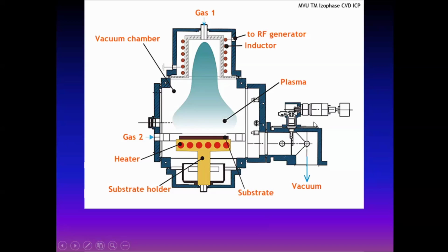So a few of the advantages of CVD: we get uniform thickness, flexibility, control of the thickness, control of the temperature, control of the flow rate of the target atoms, etc. And the major disadvantage is the toxic gases that are involved during the fabrication, right?